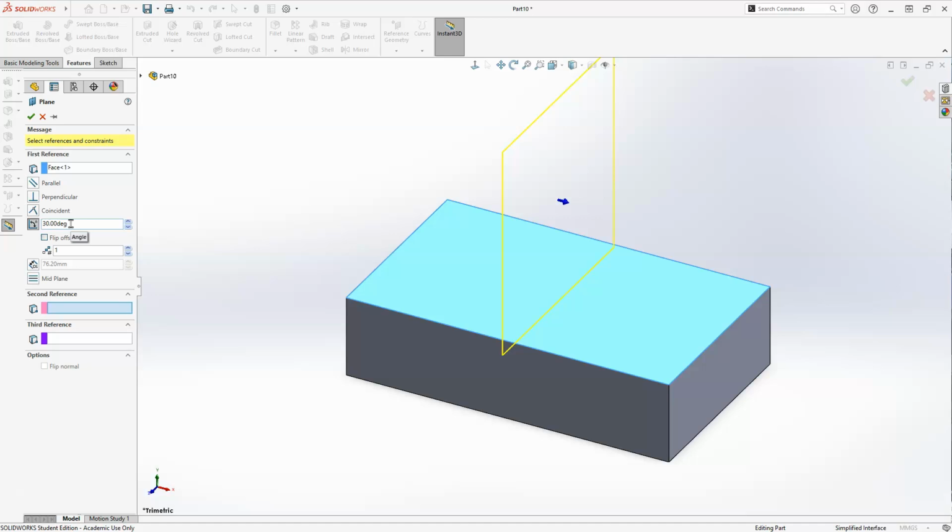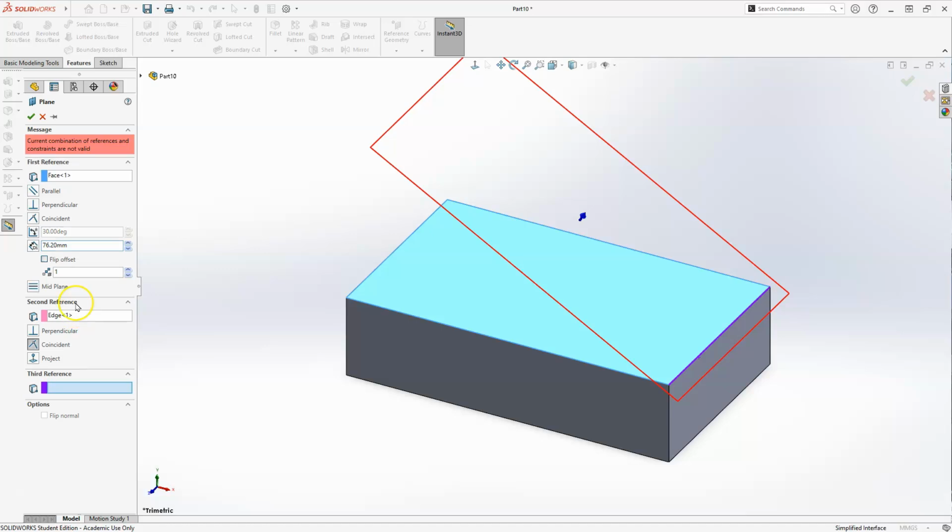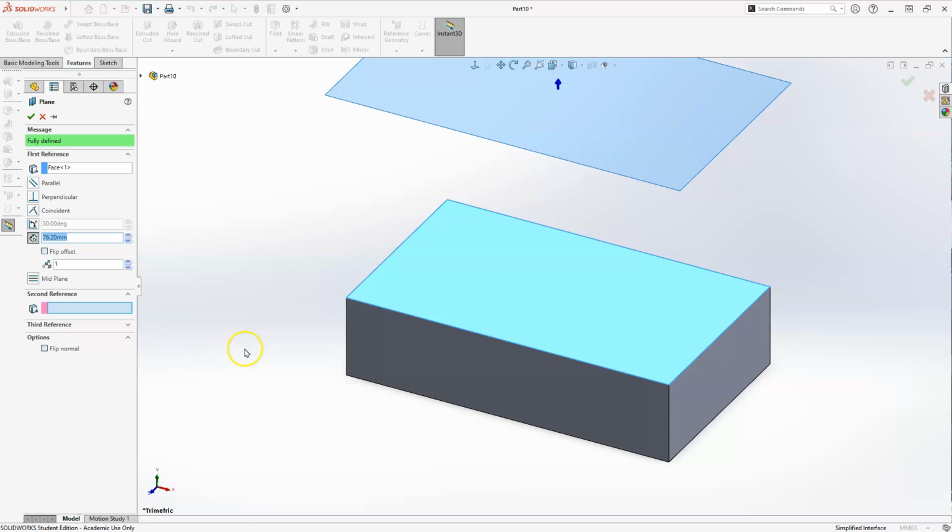Remember what we've seen in Inventor is that I have to give it a second reference and say, hey, go off of that axis. And once I do that, it'll say, okay, I can figure out 30 degrees from that. But if we were just using the regular option of giving it a distance, I don't need this here. Let's go ahead and open that back up and delete that. And now it'll give me my distance back.